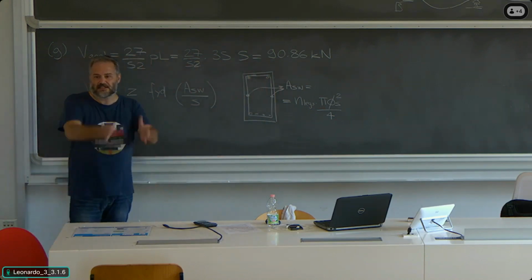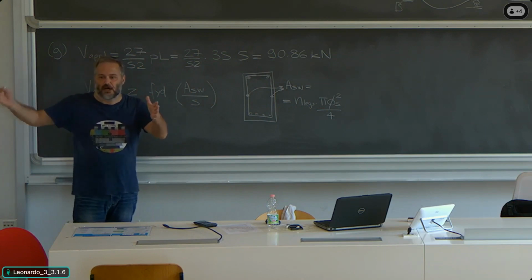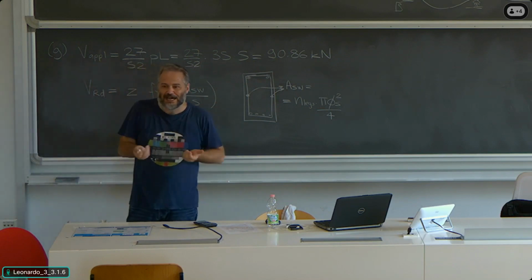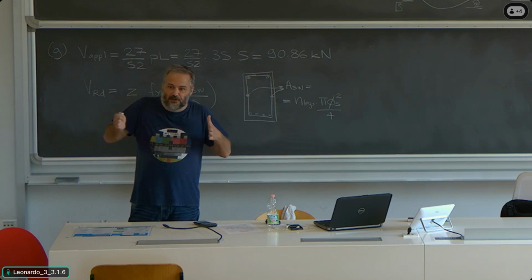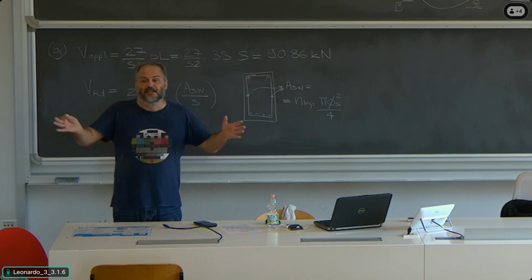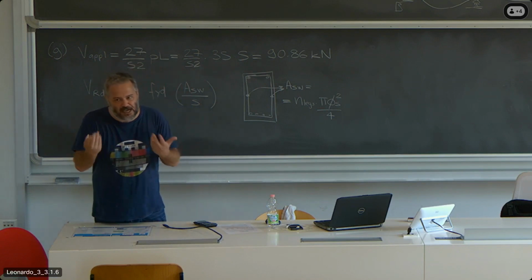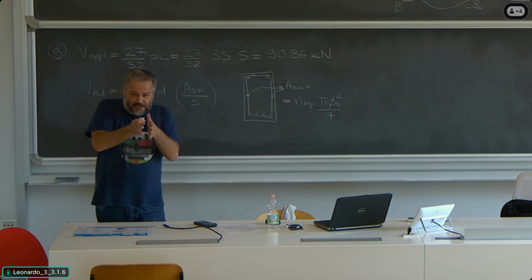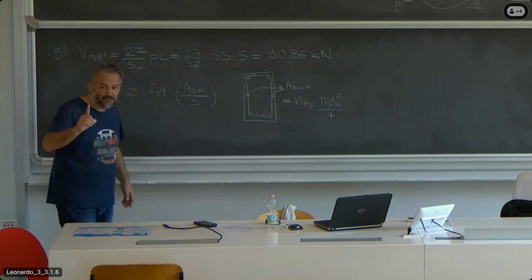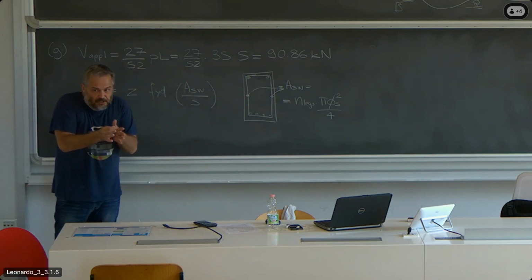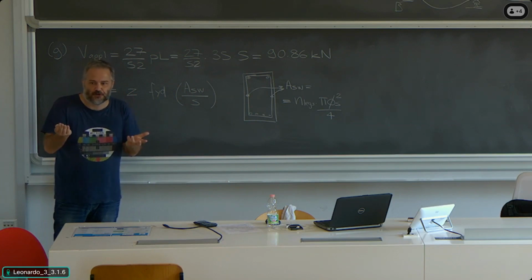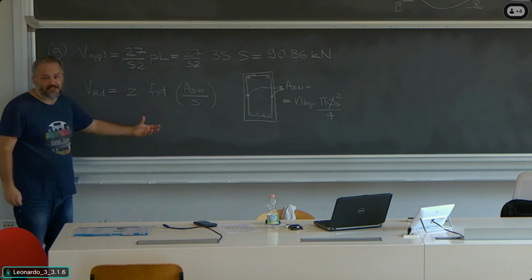The spacing is the distance between one stirrup and the adjacent one along the span of the beam. You know, the closer the stirrups, the higher the shear. The further away the stirrups, the lower is the shear the beam can sustain. So I typically expect in the supports area, where the shear is higher, to have more closely spaced stirrups, other than what happens, for example, at mid-span. Bear in mind this, the closer the stirrups, which means the lower the spacing, the higher shear force the beam can sustain.